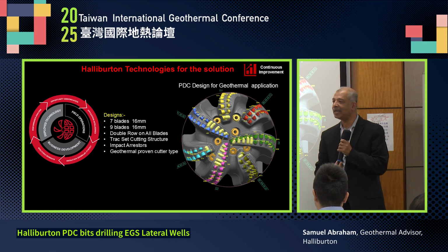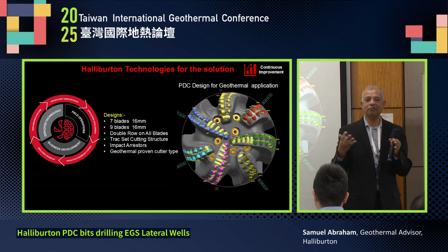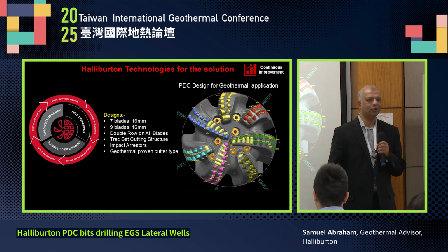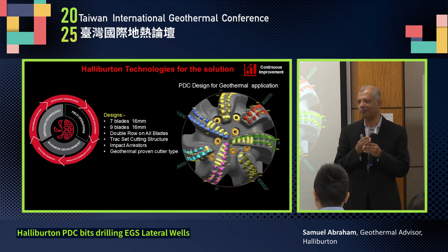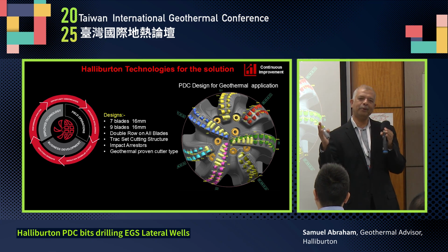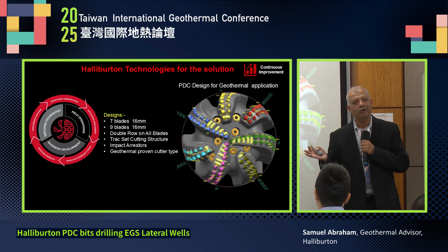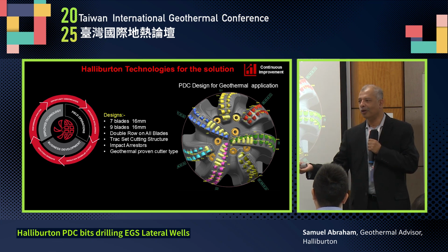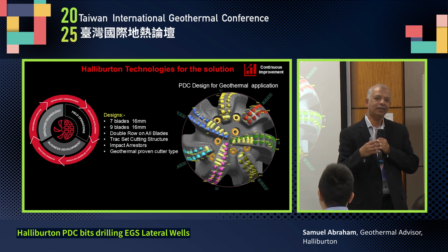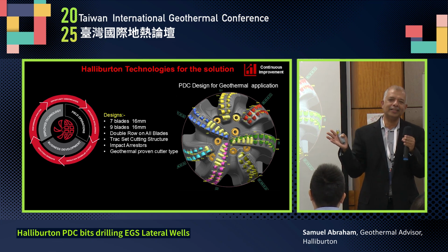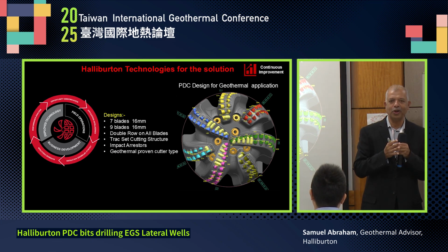Now, what is the main challenge over there? When you're drilling, everybody who does some work at home, cutting things at home, right? If you put some water, it helps to cut things better. Now, that's what also gives us a little bit of buoyancy factor and some protection from all the vibration. But the moment you lose your fluid in the hole, what have you done? Your buoyancy, anything that's giving it support is all gone. So your lateral vibrations are going to increase more.